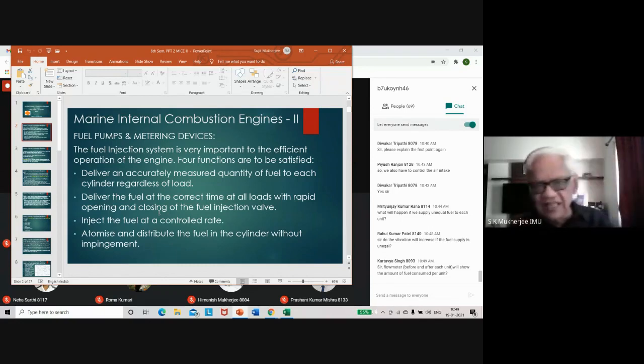Then you look at the exhaust gas temperature, and you will find the exhaust gas temperature is low. Or if you look at the exhaust gas temperature and see it is very low, and you feel the pipe and the pulse is also very low, then you immediately know that the quantity of fuel is not going in correctly, because that pulse is indicative of how much fuel is going in and the valve reseating after the fuel goes into the injector. Once the fuel is cut off, for every combustion process, there is a delivery valve in the pump, and that reseats. That impact of the seat is what sends the pulse right through the piping.